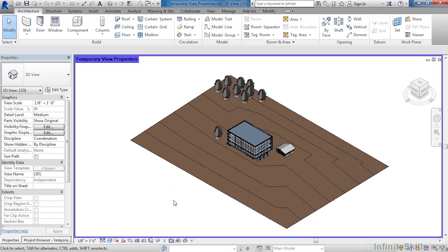When you do that, you'll see this blue or purple line going around the perimeter of your view. This means that temporarily, any changes that we make to the view properties will only be effective just temporarily. By clicking on that box again, we will then be able to shut off any changes that we make to the view properties. Move your cursor down and then select the Visual Styles button.